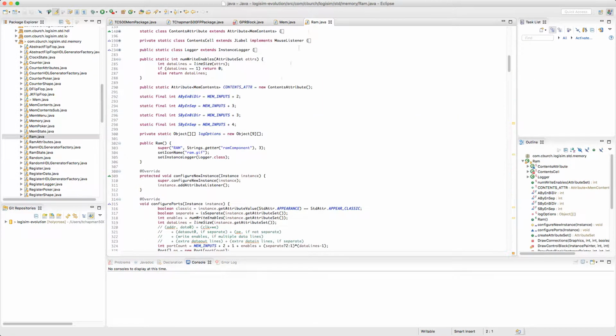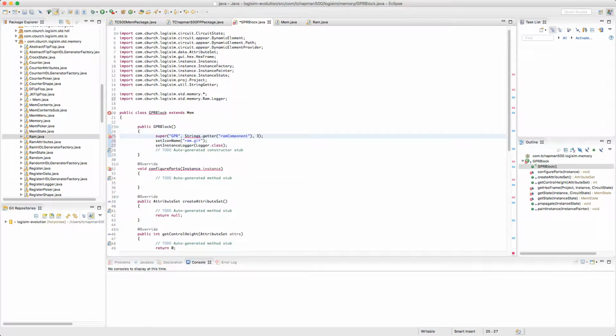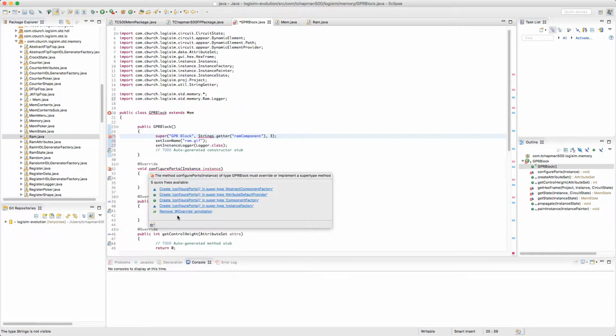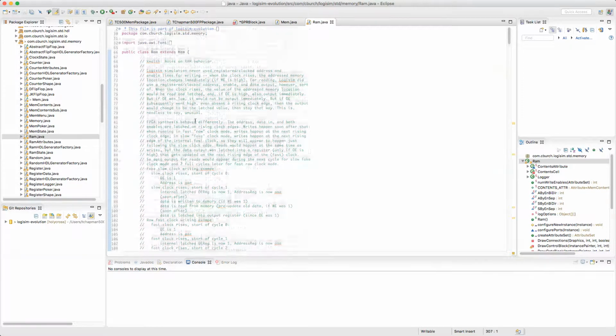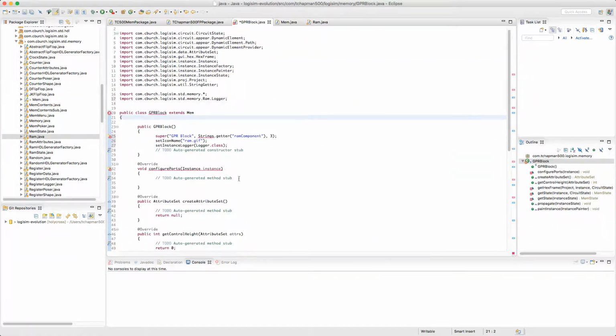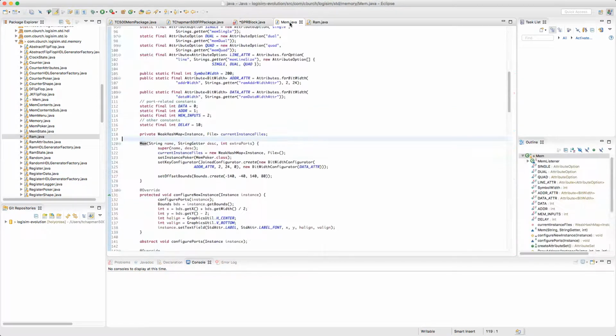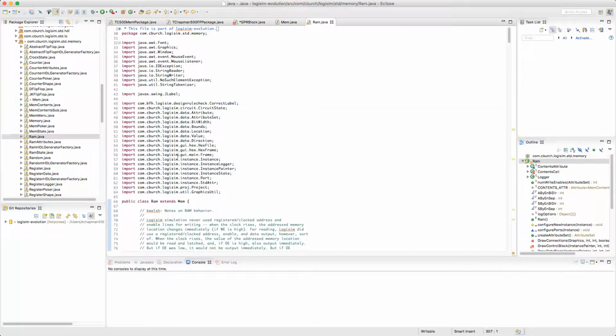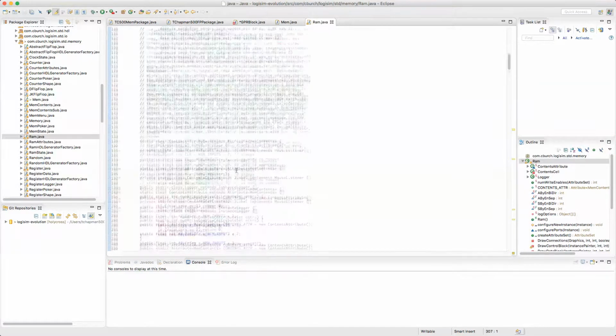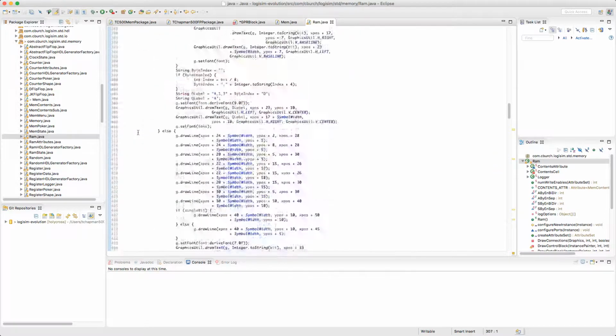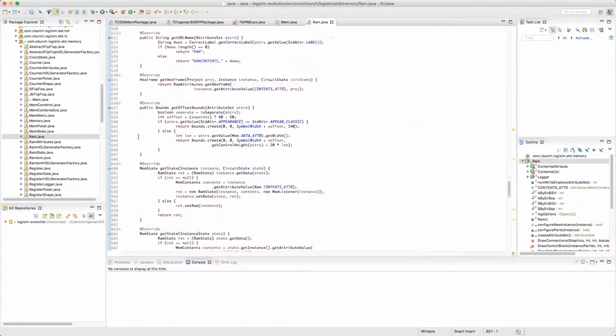Now, I'm wanting this GPR block to have an option available so that it can either take two addresses, A and B, or three addresses, A, B, and C. For arithmetic operations, if you have only two addresses, it would do something like A plus B, store into A. And for moving, it would be move what's at B into A, overriding what was previously in A.